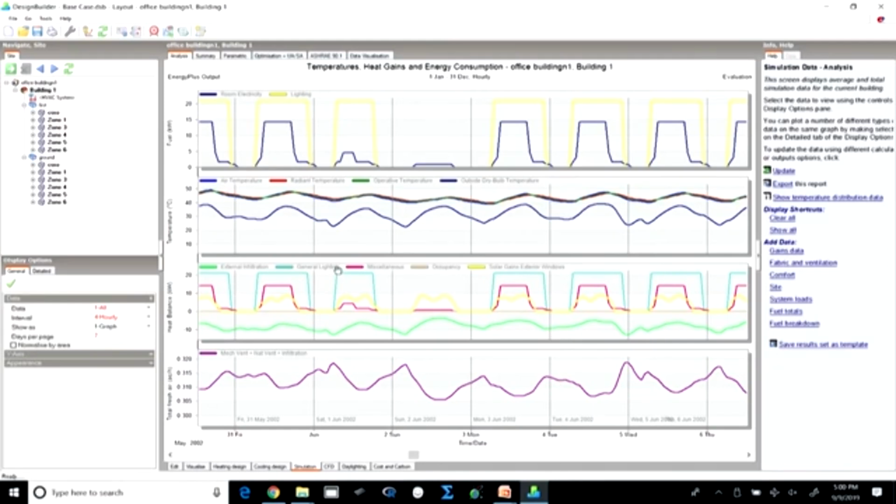If you remember, the radiant fraction of the luminaire was quite high, around 70%. So, during the office hours, a huge cooling load is added because of general lighting, which can definitely be taken care of.